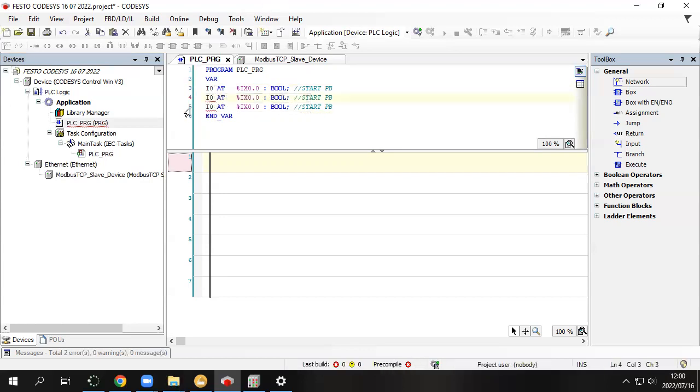Then when you edit now, because now we have errors, we're going to say I1. Then you come here. The address is 0.1. Now, it's our stop button. Stop button, PB. You can just say NC. NC stands for normally closed. Just in case you're dealing with a complex system, you can label it for yourself. All right? Then over here, we don't have any other input.